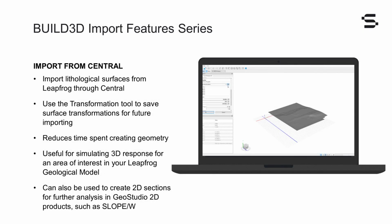This workflow is useful for simulating a three-dimensional analysis based on your Leapfrog geological model. This includes the use of a transformation tool in Build 3D, which can be used to save the transformation settings of your imported surface meshes to reduce time spent on future importing from the same coordinate system.